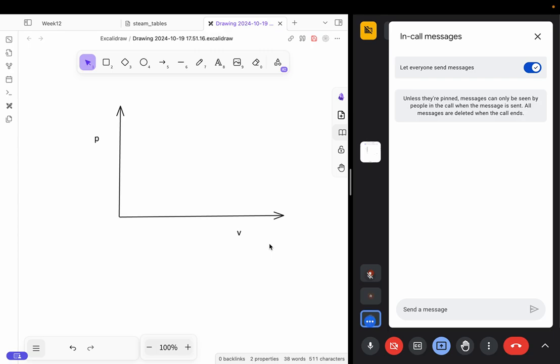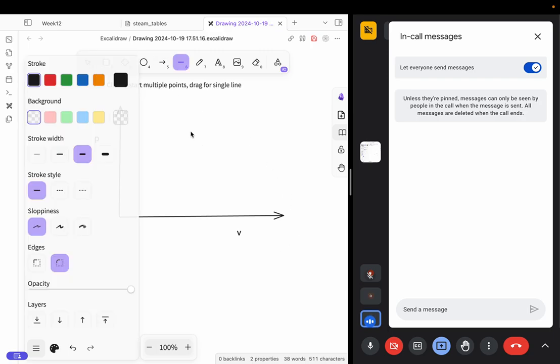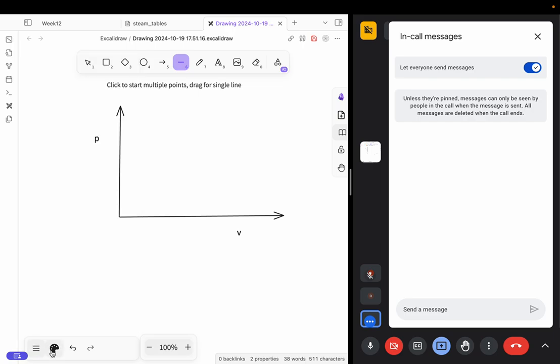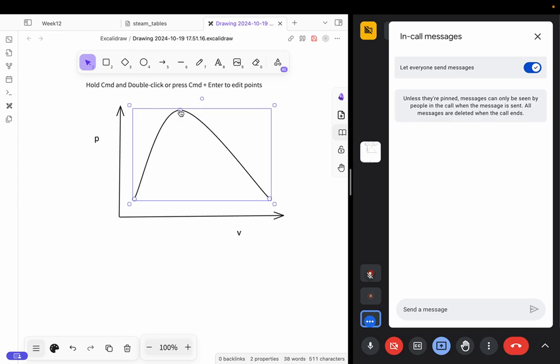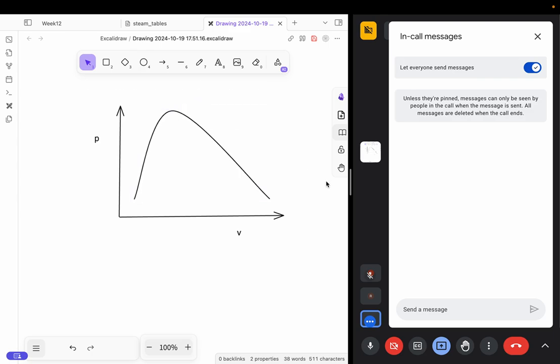So if you were to represent the processes, first let's move to the line. Now say this is your boiler. You are going from the saturated liquid state to the superheated state. So this is your constant pressure heat addition process. This is your turbine inlet. From turbine inlet to turbine outlet, you should be following the isentropic process.